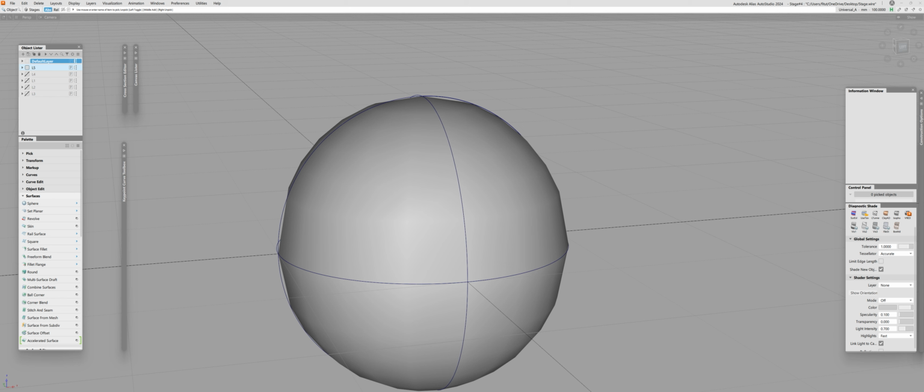And fourth is the refinement. So the density of the tessellation, which means the number of polygons, can be controlled to balance between, let's say, the visual accuracy and computational efficiency. Higher density tessellation will yield smoother and, let's say, more detailed surfaces, but require more processing power. And that's exactly what you will do when you move the tolerance slider. So this is the tessellation slider, actually. So in the end, this process allows the curved surfaces defined by NURBS to be visualized and manipulated, so modeled, using polygonal meshes. That, let's be honest, is the staple of real-time graphics in most 3D modeling applications. Essentially, it's about finding a practical middle ground between mathematical precision and graphical efficiency.